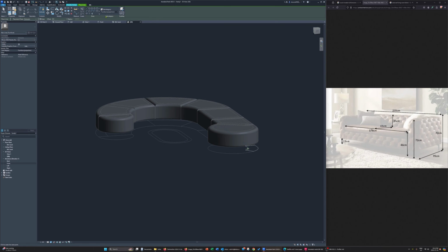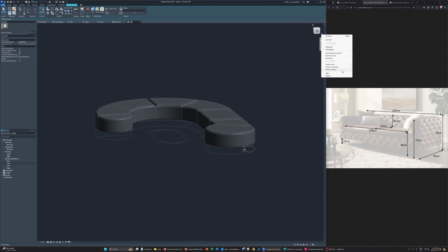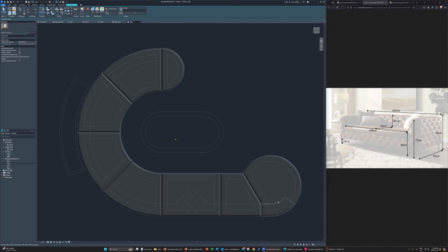Potentially I'm going to be able to modify the sweep. Did I set this in the correct work plane? Sure I did. Just consider it this way. And once again, I'm going to reorient to a plane. And I'm going to use not my extrusion, but my work plane.